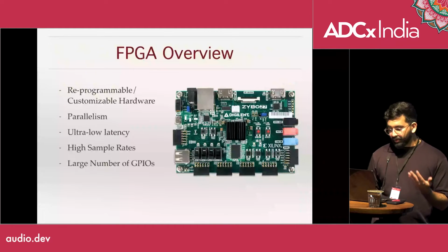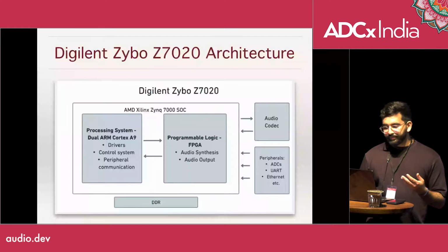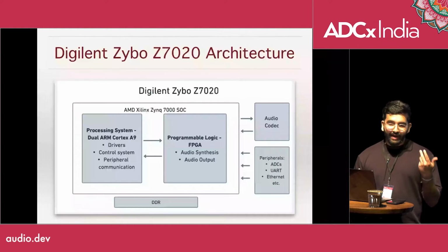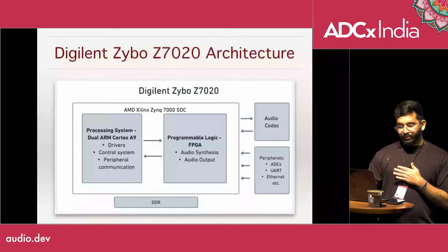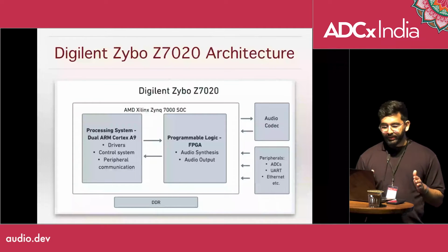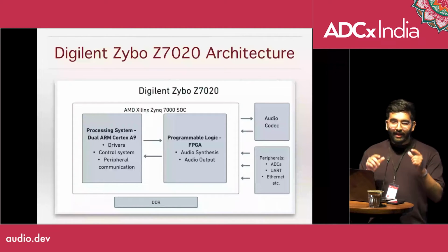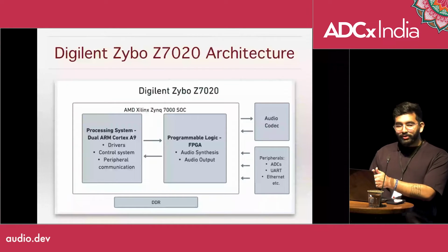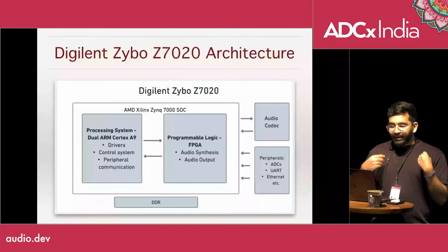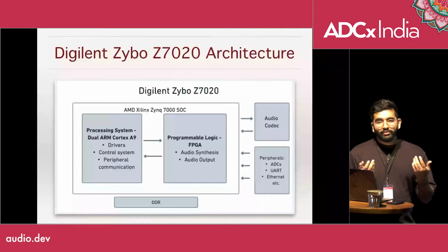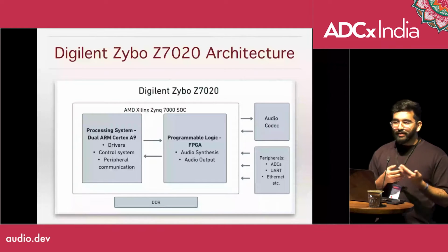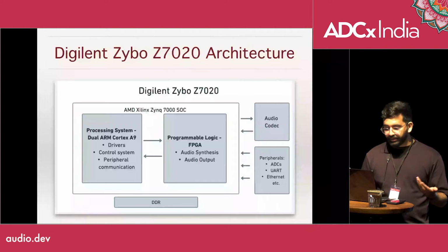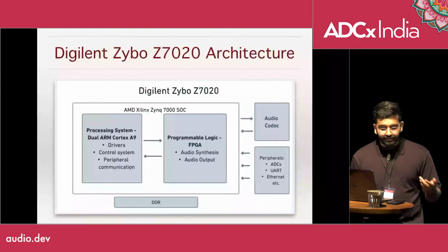It is actually a system on chip, which means that it's not just the FPGA on the chip. There's also some memory, BRAM memory, and there's also a dual-core ARM Cortex processor, so just a CPU. So on that single chip, there's a processing system and the programmable logic, which is the FPGA part. And one of the challenges with working with these chips is balancing what you put on the CPU, what you put on the FPGA, and how they are interconnected and interfaced as well.